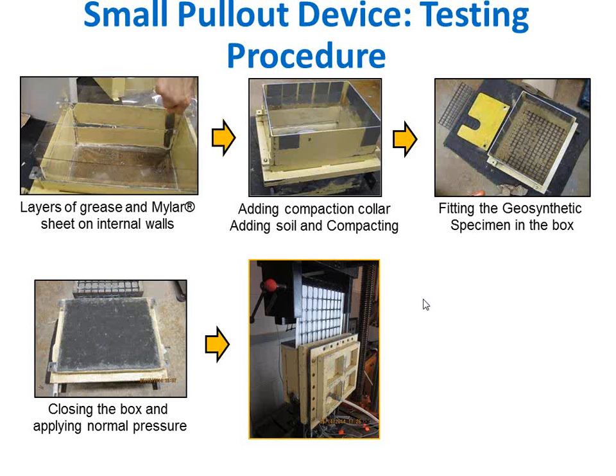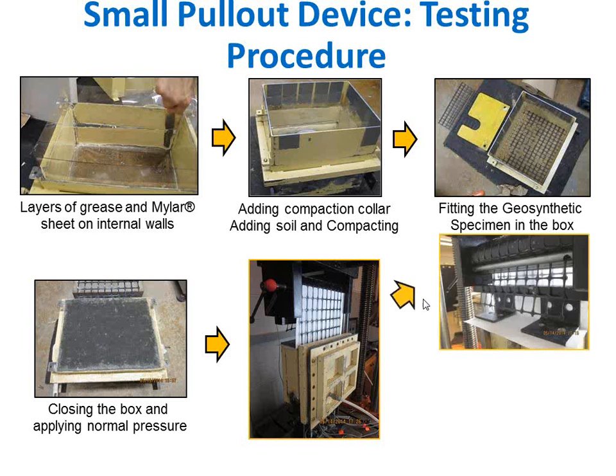So there's strain in here. We monitor the strain of the unconfined portion, and we get the tensile strain response of the unconfined reinforcement, and we also monitor the stiffness of the composite. We are kind of concluding, but not yet, that what we initially called the confined stiffness is very close or very often the same as the unconfined stiffness that we're obtaining. That will be later on.